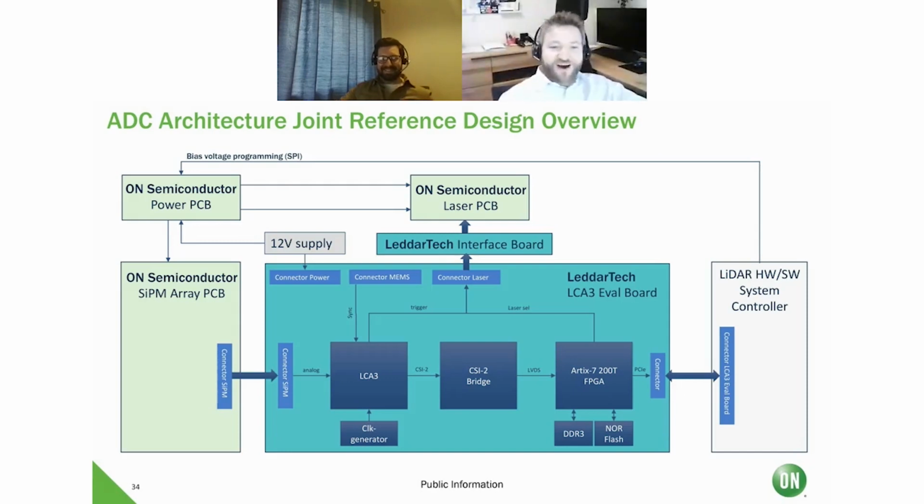Thank you. On the LCA3 eval board, as said before, we have the LCA3 ASIC, with an additional clock generator. Then we have a CSI2 bridge. As I said before, parts of our signal processing are placed not only in pure software, but also supported by an FPGA. That's why we have this CSI2 bridge with the connection to the signal processing in the FPGA.